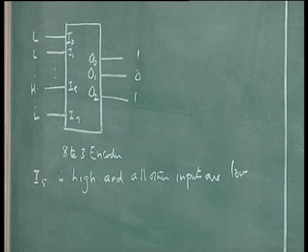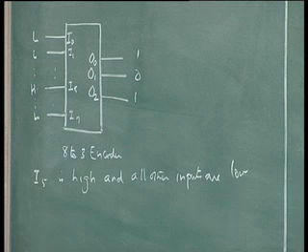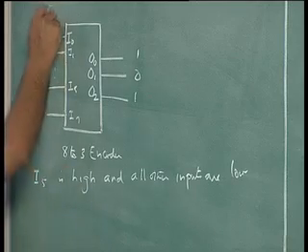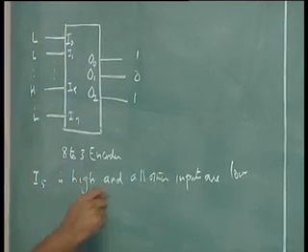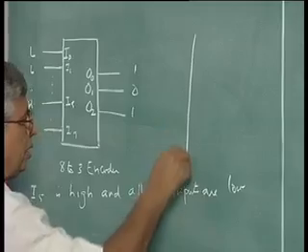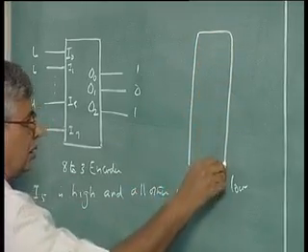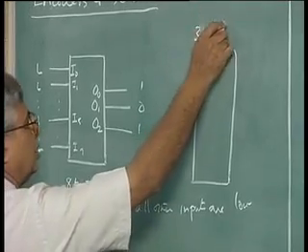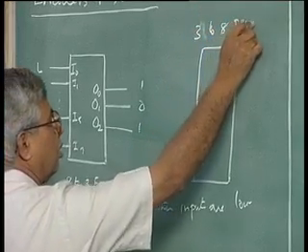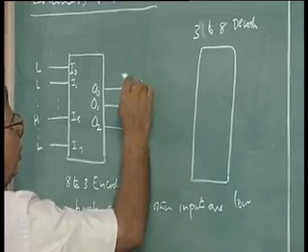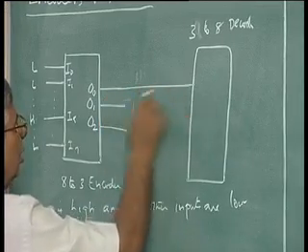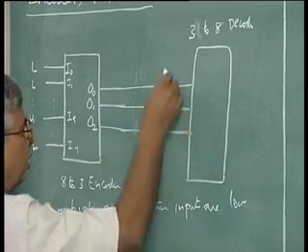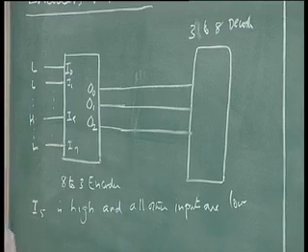The reverse of this, the complementary operation, is called the decoding operation. So, this is an encoder, 8 to 3 encoder. So, we will have a 3 to 8 decoder. I can put this here straight away, 3 to 8 decoder, 3 inputs. Now, there is not just one of them, because any combination of this can happen, because there will be 8 different outputs, the corresponding output will be high and all others will be low.